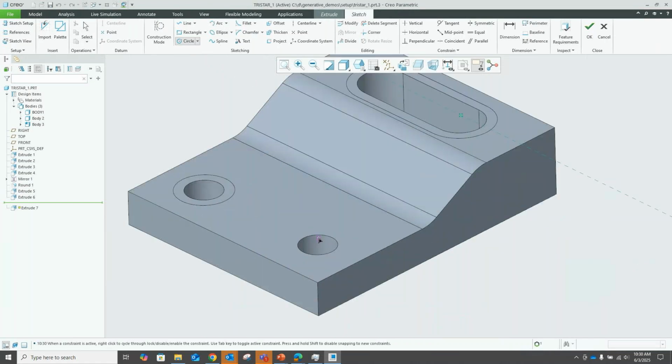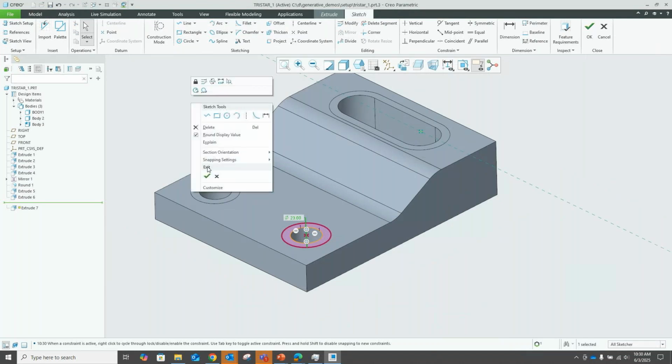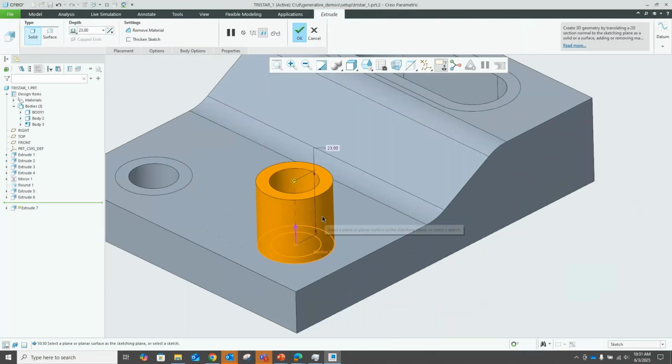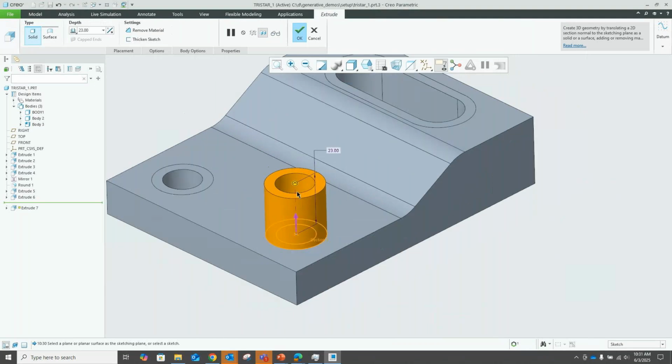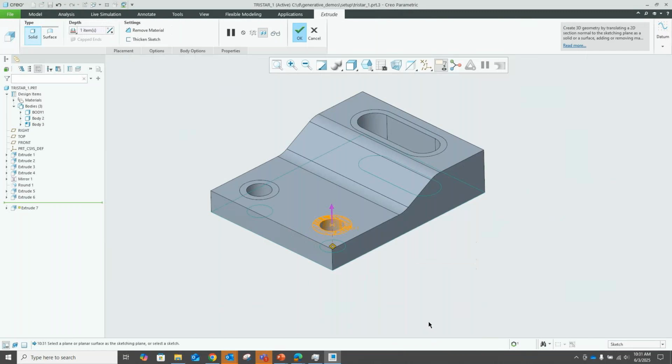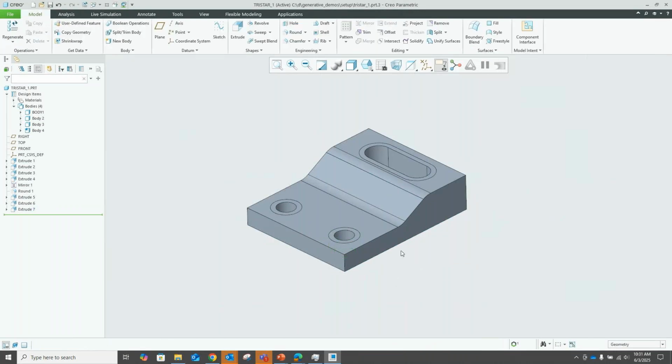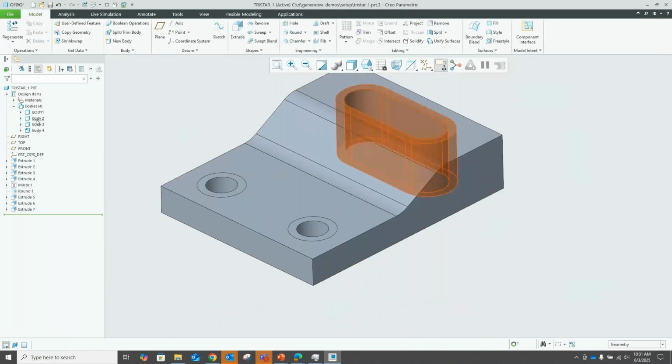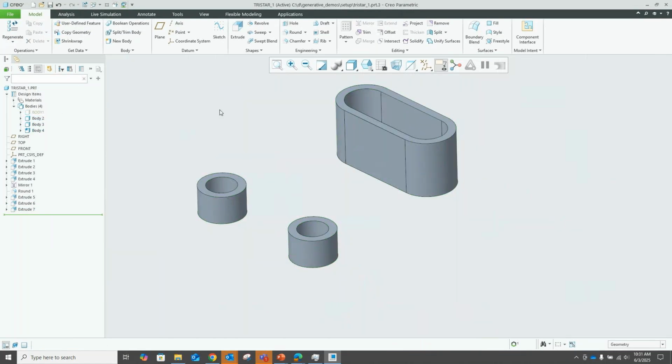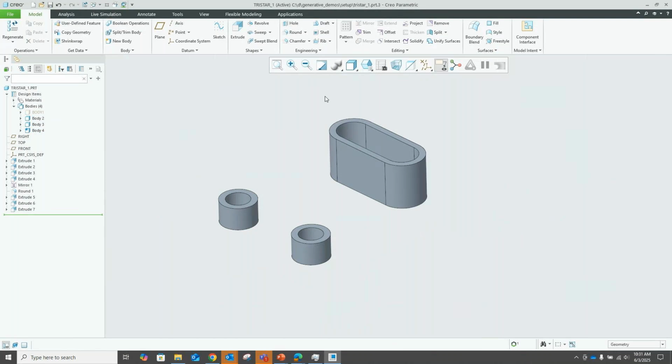That's what I'm going to do here, and maybe I'll just use it as a reference. And we'll just specify some known dimensions here. It's great to see when everything's already set up, but what it takes to set it up from scratch is what I'm showing you here. And if I create a new body, there it is. So we got 4 bodies at this point, body 1, 2, 3, 4, right? So if I select these 3 bodies and isolate, you get the idea. I'm essentially telling it these are my preserved volumes, if you will.